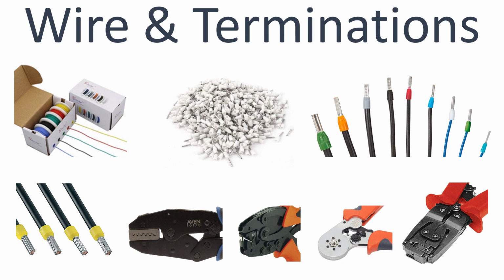If you look down in the bottom row, you see 4 different shapes. The first one on the left is probably the best, simply because it's more flat and it'll slide underneath a pressure pad underneath a screw better. And if you look at these crimpers, the first 3 give you everything but a flat crimp. The 4th one, which is the one I have, you put the ferrule in there and it crimps it nice and flat. The downside to that last one is $235 to buy the tool. If you're going to do a lot of crimping, you want that last tool. It'll last you a lifetime and you'll never be disappointed in your crimps.